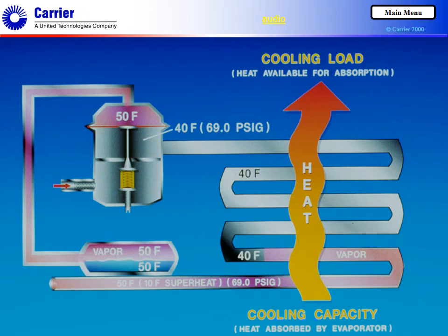The sensing bulb is designed to sense refrigerant gas temperature. It should not be located on the bottom of the suction line or other places where it will measure the temperature of liquid refrigerant should it accidentally enter the suction line. Once installed, it should be wrapped with waterproof, usually closed cell insulation, right along with the suction line. The insulation should extend at least 1 foot beyond the bulb in each direction. Always consult the equipment installation instructions for the correct location of the bulb.